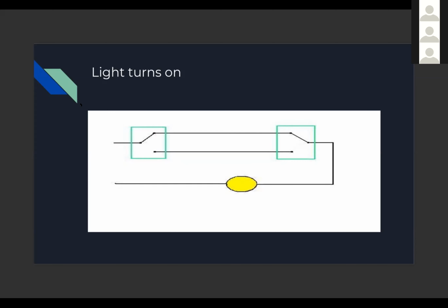The switch on the left, which he very clearly articulated, the wire coming in comes from the panel. So that's coming from your breaker panel. And that switch then has two wires that leave it that go to the other switch. They don't go to the light bulb. So lots of people are confused about that. So when you start wiring homes, you have to think carefully about how these switches are connected, because it's not the way you think. Thanks, Marcel, for sharing that.